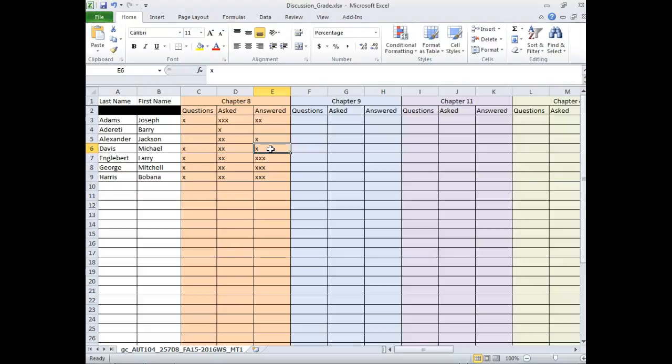It's in the name, thermistor, right? A resistor that changes its resistance with temperature. One of them is a positive temperature coefficient. One of them is a negative temperature coefficient. So which one would go up if the temperature goes up, the resistance goes up? A positive. And the other one, the resistance will go down if the temperature goes up. Most of your thermistors are NTCs. All the thermistors that we have that I'll show y'all in class are NTCs. So that means when they get warm, their resistance goes down.